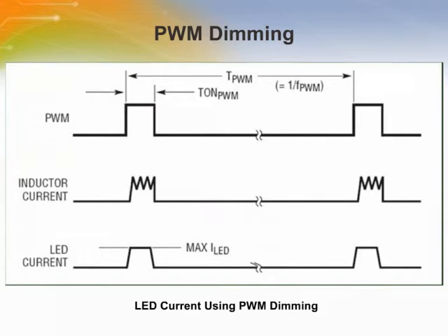For true color PWM timing, the LT3598 provides up to 3000 to 1 PWM dimming range. This is achieved by allowing the duty cycle of the PWM pin, which is connected to the IC and an internal switch in series with the LEDs, to be reduced from 100% to as low as 0.1% for a PWM frequency of 100 Hz. PWM duty cycle dimming allows for constant LED current to be maintained over the entire dimming range.